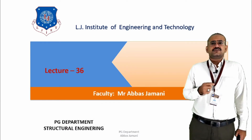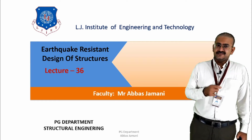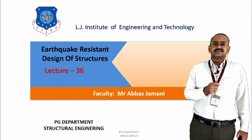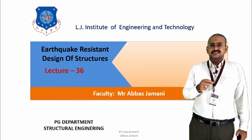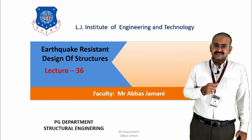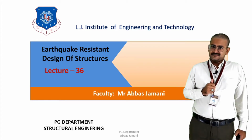When I am talking about the combined modes, the code discusses basically two types of methods: the first is known as the SRSS method and the second is the CQC method. Today's example is based on these two methods, that is how to calculate the values of combined storey shear and combined lateral forces based on the mode shapes that we have. Let us start today's lecture, where first we will take up the CQC method, and after that we will look at the example of the SRSS method, right?